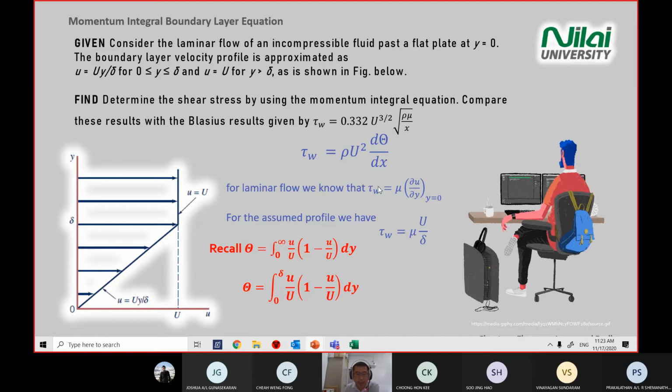So in this slide we first take the laminar flow definition and link it up with the shear stress, modifying it accordingly to our case. Then we call out the momentum thickness and modify the boundary condition, because the original is from 0 to infinity, but in this case we are only interested from 0 to delta. The content is still the same; only the boundary condition changes.